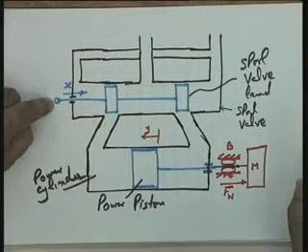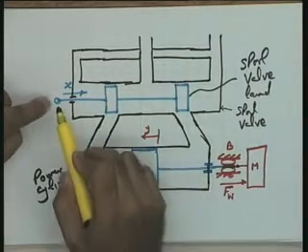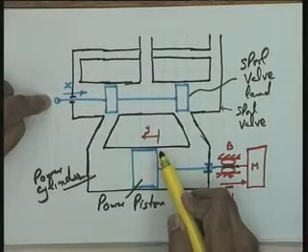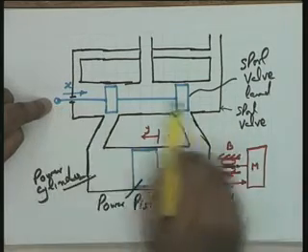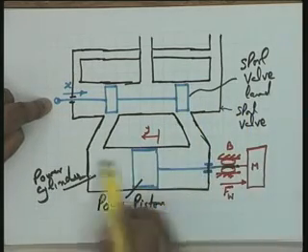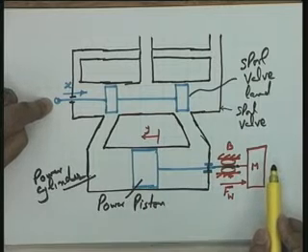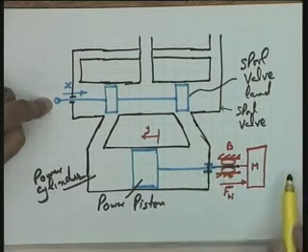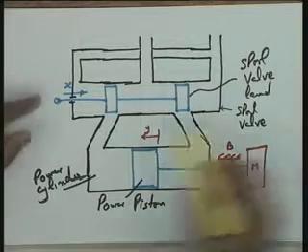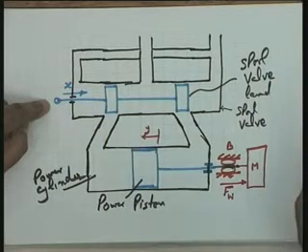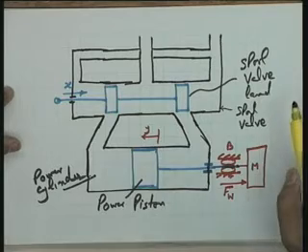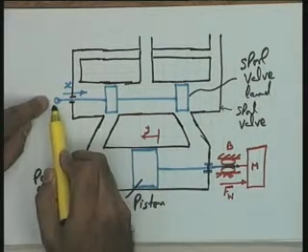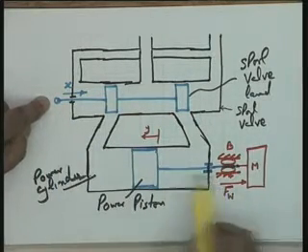For a hydraulic motor, the input and output variables are the following. X is the input and Y is the output. The only thing is that the X input requires low power because this is a lighter spool, while the Y movement is created at high power because it is able to move this particular load. So effectively, if you take input as X, which is displacement, and output as Y, which is again displacement, this particular linear actuator is nothing but a power amplifier. Low power at this point gives rise to high power at this point, which is able to move your load.